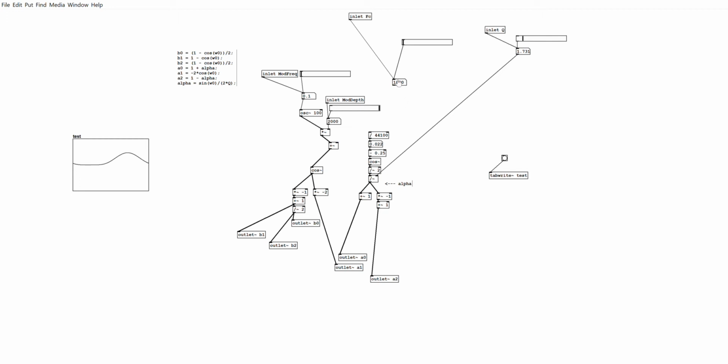I've made a mistake here. So the modulation frequency, of course, can be anything you want. For an LFO, that might be something at 1 hertz or even lower. And the depth will be how many hertz we are modulating by directly. So if I am adding to FC, then I'm basically just changing FC as a function of time.